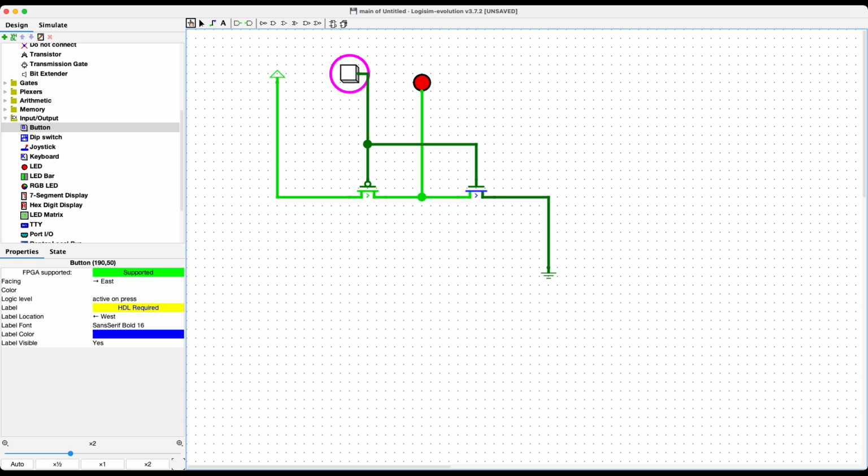The spring thing, I'm thinking of those as being the individual transistors, but I put two of them together here. So if my input is a 0, what's my output? If my input is a 1, what's my output? What is that? That's a NOT gate. So this is a way to build a NOT gate with MOSFETs. It's not the only way, but this is a way, and this turns out to be the way in terms of modern fabrication.